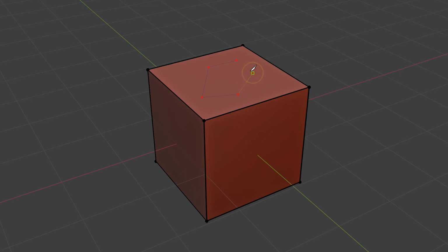To enclose the area, we can either click back on the starting point, or we can double-click, and Blender will add a final edge to complete the enclosure. It also takes the double-click as a sign that we've finished that sequence of cuts and allows us to move the knife to a new location without assuming a new edge should be joined to the previous location.